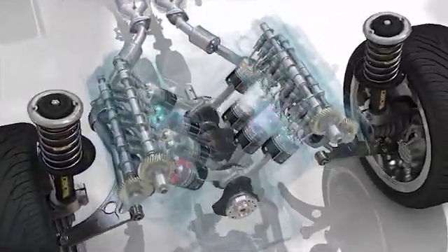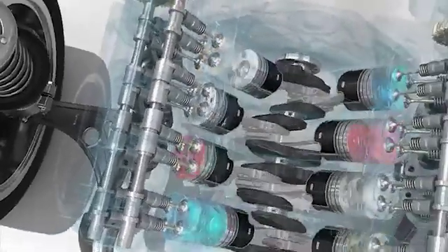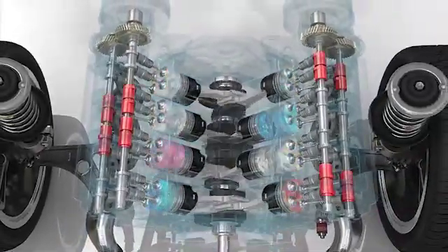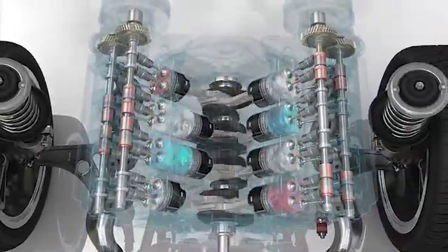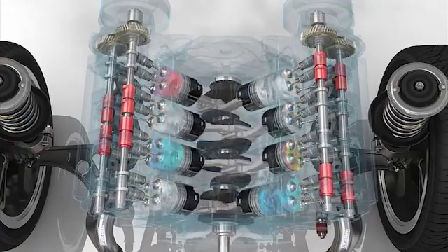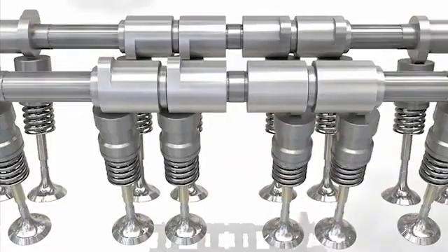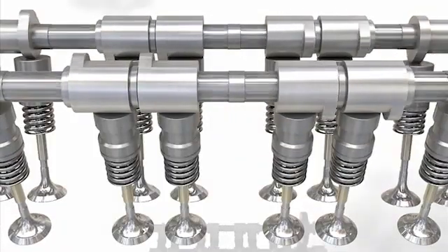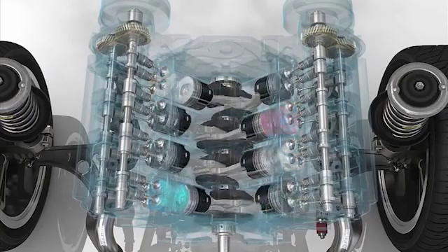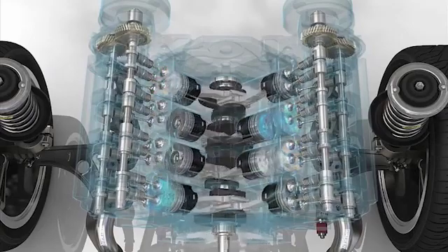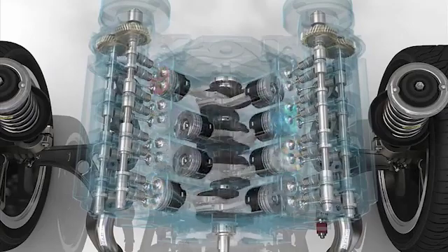Recently, some vehicle manufacturers have presented solutions such as engines with selective cylinder deactivation, depending on the load. In these engines, when the vehicle needs little power, i.e. when operating at low speed without accelerating, the system disconnects half the cylinders, thereby reducing the fuel consumption.